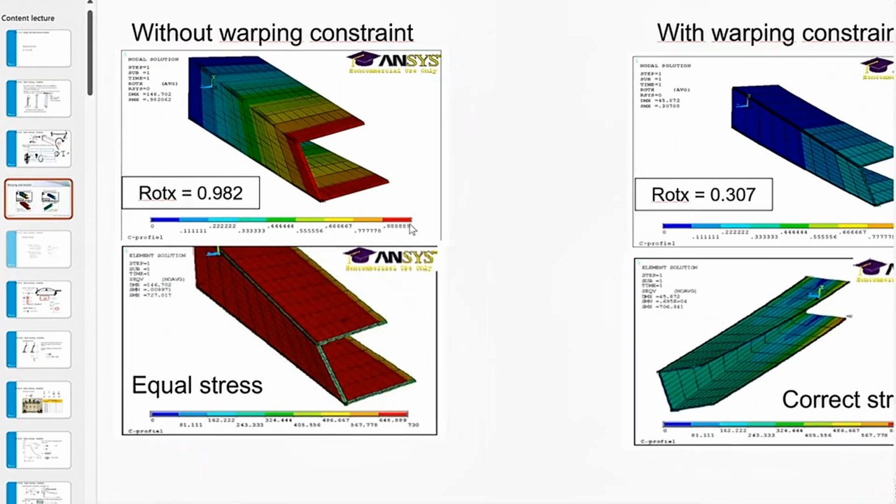If you do not take into account this shear strength, so the stresses over the section itself, then you have standard beam theory, and you have a deflection which looks like this. So that is a constant rotation if I apply a constant torsion. You see here the deflection. So the rotation varies constantly over the length.